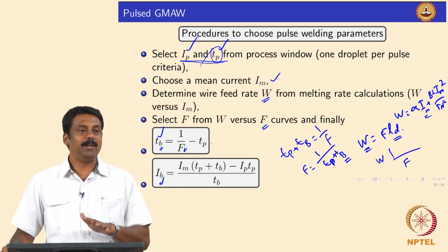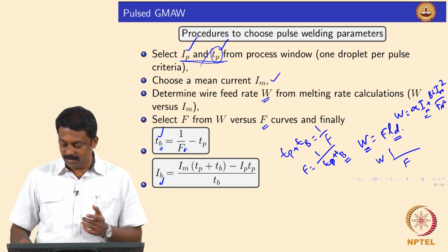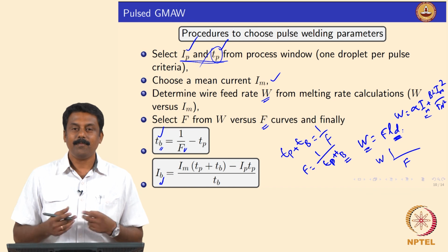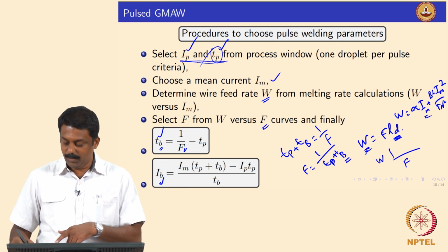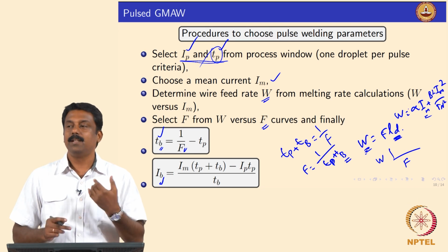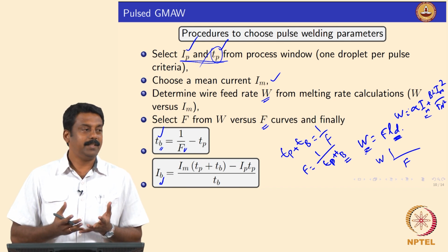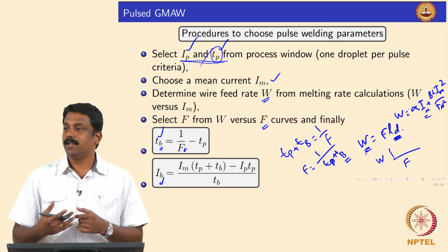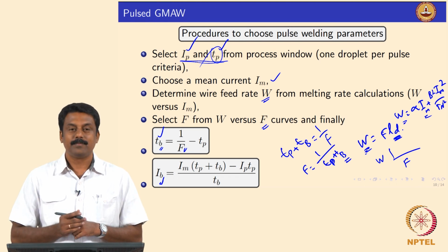Okay. And then it will also identify what diameter you will use, because diameter is very critical as it determines your LD. So, for a given LD, you will have to identify W, and W again is determined by the composition, because composition contains your H and Cp, right, isn't it? Latent heat of melting is there and then Cp is there, that will be used to calculate the melting rate, isn't it?